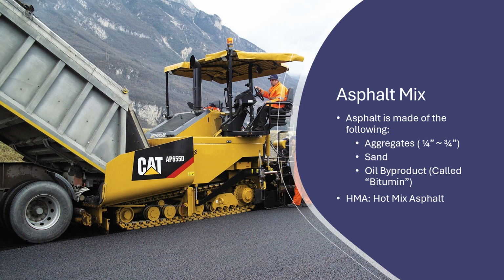I should mention there is such a thing as cold mix asphalt. It's never ever used to pave roads. That would be pretty disastrous. Cold mix asphalt is really meant for just small patches. It's really seen as a temporary structure. You would almost never see that on a highway. I used to install cold mix patches in parking lots for retail stores, maybe some small residential roads, but nothing bigger than that. And so any large patch, large road, you're going to use HMA.